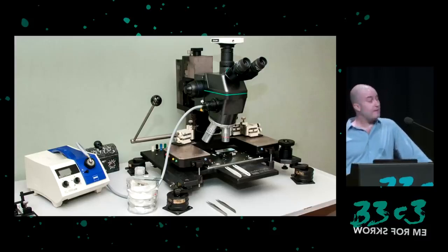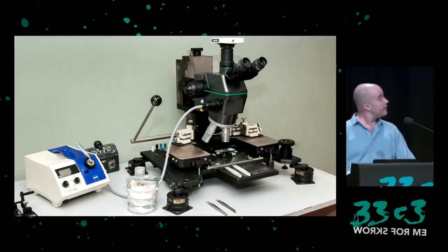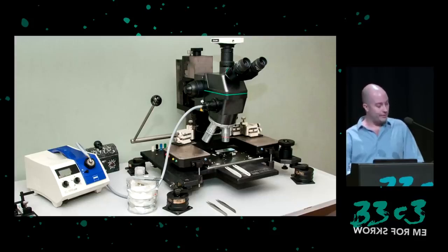So next I started an invasive study of the chip, studying it under a microscope. The cost of microscopes can range from hundreds of dollars to tens of thousands of dollars, or even higher for things like electron microscopes or other specialized equipment. I have a couple of microscopes that I use. This one is the Mitutoyo FS70 microscope. These Mitutoyo microscopes are often used for microprobing, but you can also use them for other purposes.